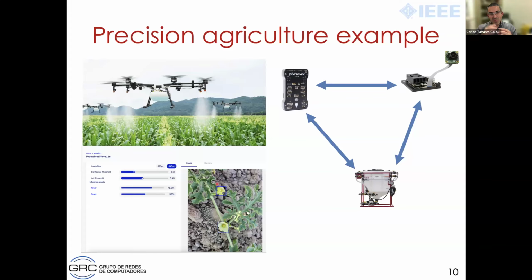There can be other cases where what you are learning is from very high altitudes, to detect some features in the terrain. For example, if you want to fly around without GPS and just rely on the image sensor to locate yourself, then you can have a previous training with the satellite images and correlate with what you are currently viewing, and then you can geolocalize yourself. In fact, we are also working on this problem right now. But that is a very particular case, and it also assumes that the UAV is flying at a moderately high altitude to have a broader view of the artifacts on the terrain. So depending on your goal, it can be possible, but I think that for most applications, you will not have enough quality data for this training. That is my impression.